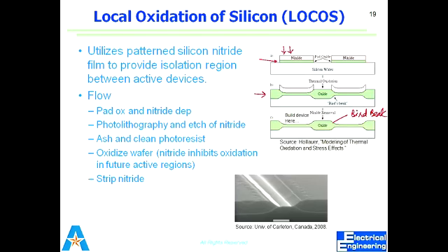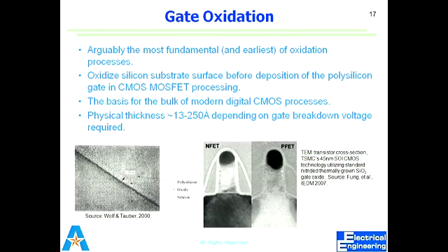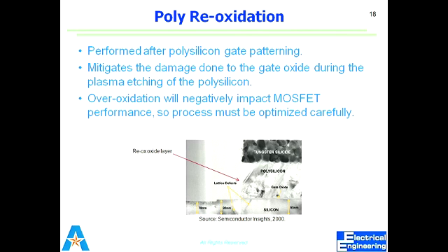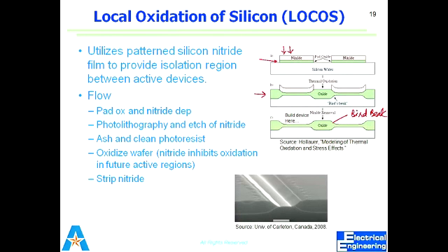In the gate oxide, we etch that oxide layer, but because of the etching process, it is over-etched and not very accurate, so we need to deposit the polysilicon again. But make sure it is a very optimized process, because when we deposit the polysilicon again, you may over-deposit it. So in case of gate oxide, it should be a very optimized process, because your etching process and your deposition process need to be very specific.